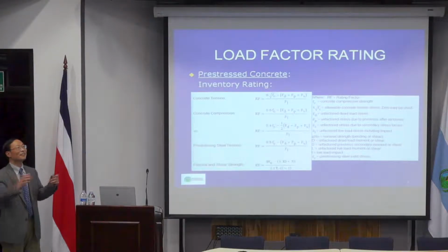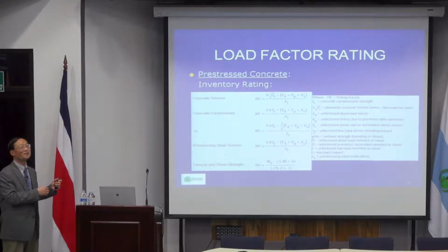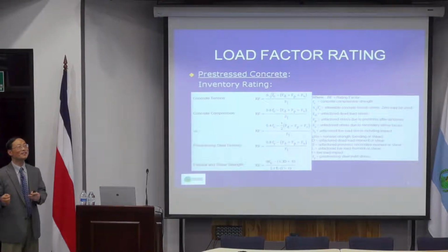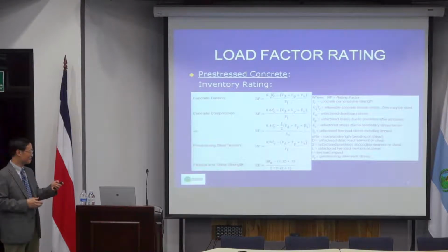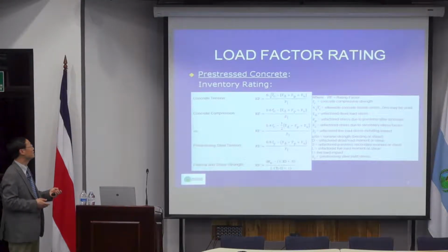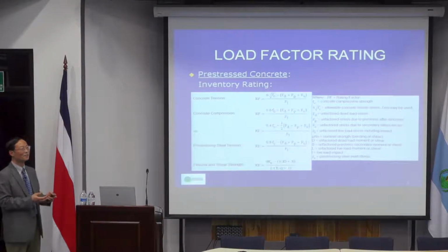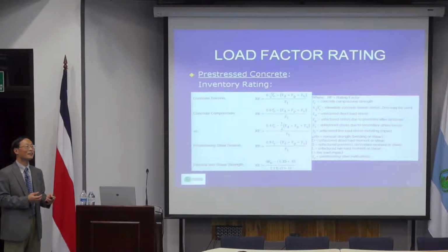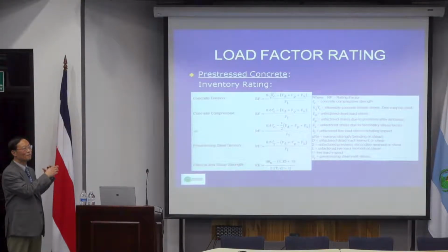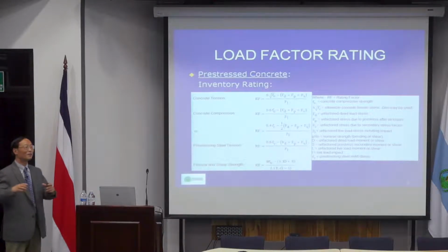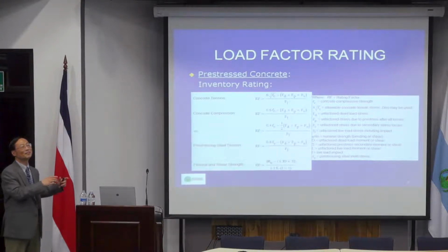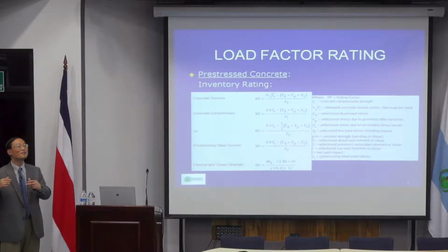At that time, most countries already used LFD. So when pre-stress was introduced by AASHTO, they just used the same concept of LFD, so there was no separate allowable stress design or load factor design. It's just one combined design. You design the bridge not only for safety, but also for serviceability. Safety means bending and shear capacity. For serviceability, you also need to control cracking and deflection, that kind of thing.